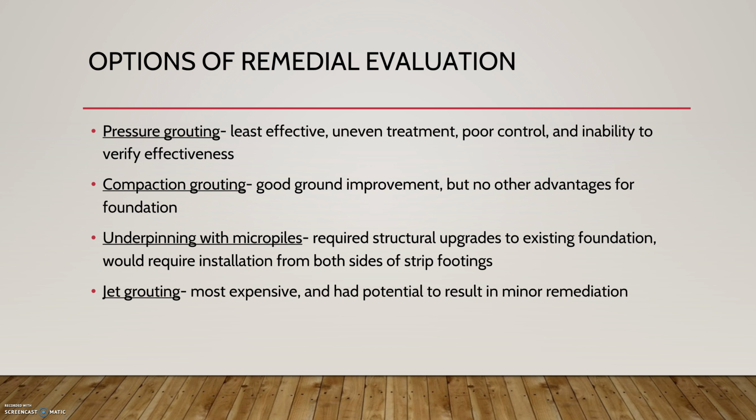So I'm going to talk about the pressure grouting, which was the least effective, and it was uneven treatment, poor control, and the inability to verify effectiveness. The compaction grouting was good ground improvement, but no other advantages for the foundation were found by using compaction grouting. The jet grouting was the most expensive and had the potential to result in minor remediation.